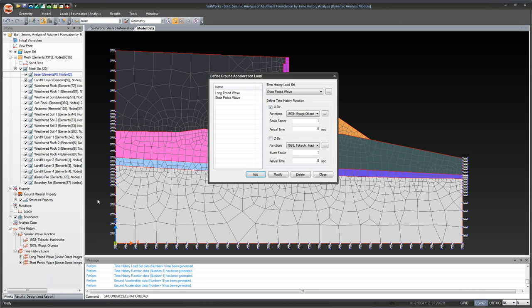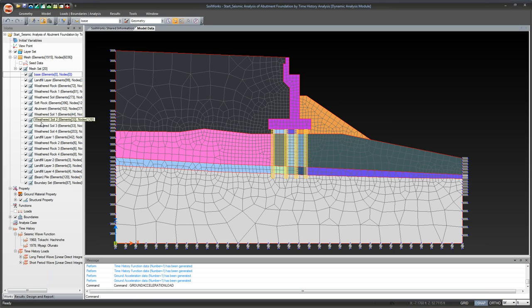Okay, so it's really important. Whenever you're doing any sort of project, this is very key: make sure that all of your material properties and all of your loadings are in black. If one of them is in blue, that means one of them is currently not in use. You need to go back and see how to assign it. The only thing that can be in blue is the base here, which is just a default mesh set, which if it isn't actively in use, it's all right, as long as the ones below it are. So that's another important thing to check for.